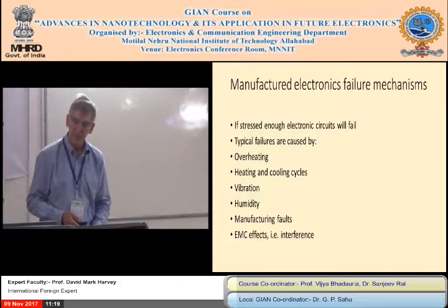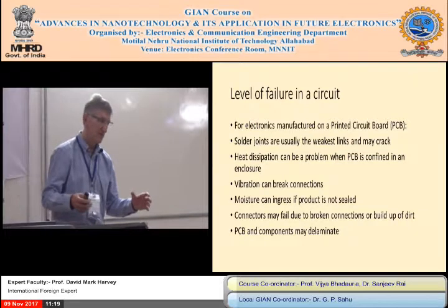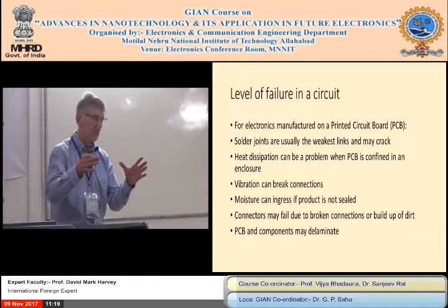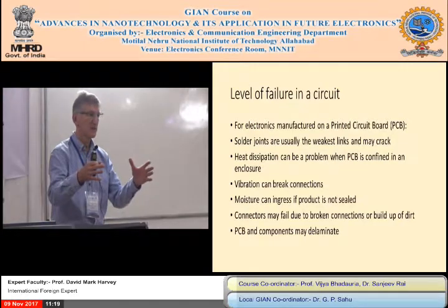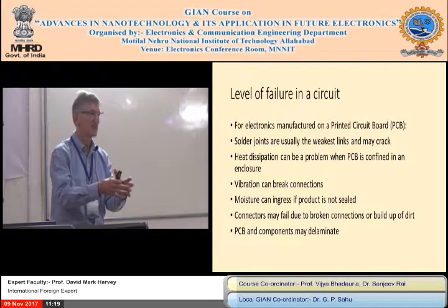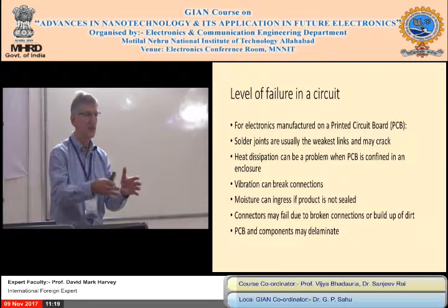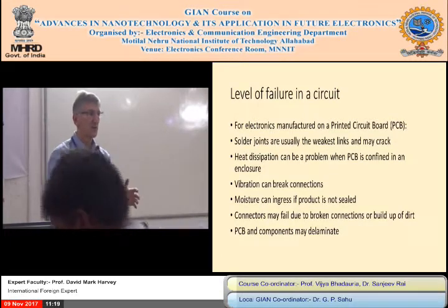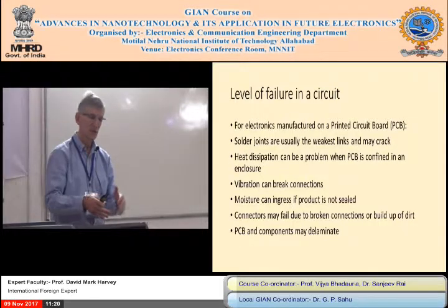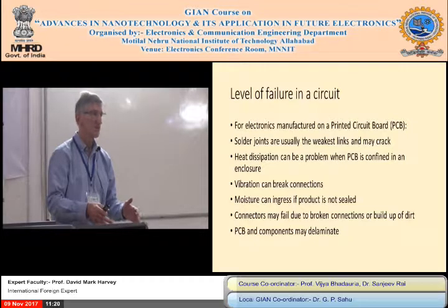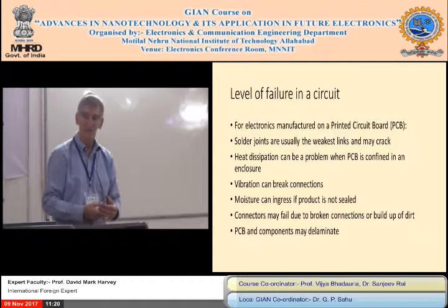If you look at the chip, you imagine the biggest wafers we're making now are about 300 millimeters, or 30 centimeters, in diameter, quite big. Think how small the transistors are now, 10 nanometers. You get a lot of silicon die on that chip, all made in a production line. It's very difficult to make that chip. So you've got to test every single die on that chip. And the yield is essential. If the yield goes down to a low level, you can't make it commercially.